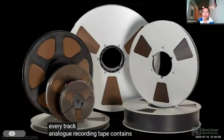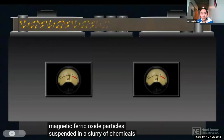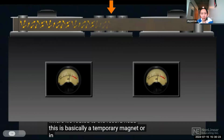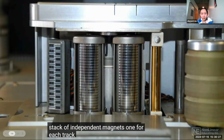Analog recording tape contains magnetic ferric oxide particles suspended in a slurry of chemicals and binders. The audio signal, the voltage to be recorded, is sent to the tape recorder where it's routed to the record head. This is basically a temporary magnet, or in the case of a multi-track recorder, a stack of independent magnets, one for each track.